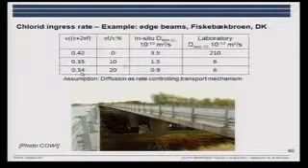Okay, so we see we have these equivalent water cement ratios, and we have an increasing amount of silica fume to cement. We have no silica fume, 10% and 20%. Then these are the apparent diffusion coefficients. They have drilled out a core, taken it to the lab, ground it, taken samples from different depths, analyzed them for chloride and got a chloride profile, and then they have calculated the diffusion coefficient which would give rise to this chloride profile.